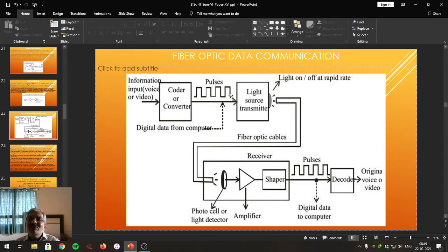So, this signal is going to vary within the bit period. During the allotted bit time, a number of digital pulses are passed, and within that particular time, the amplitude level of the carrier wave is changed. If the signal is present, it is to be treated as 1. If signal is absent, then it is to be treated as 0. If signal is present, carrier wave amplitude will be maximum.